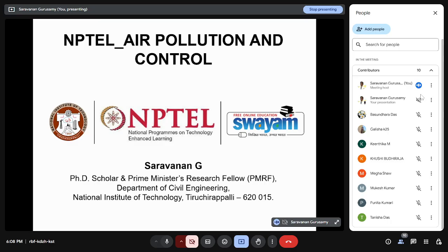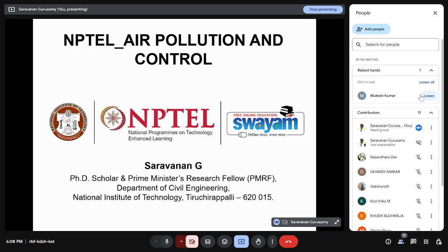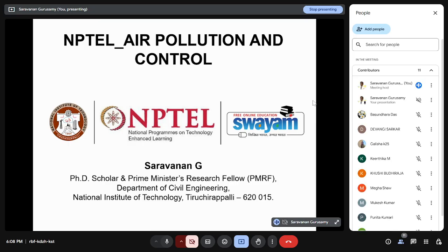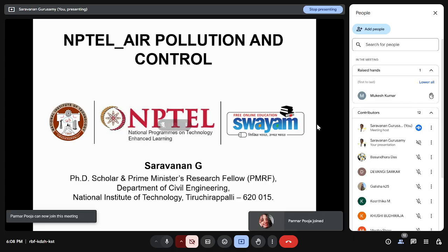Okay. So, in the second week, we discussed the sources of air pollutants, classification, and transformation of air pollutants, like dispersion, diffusion, advection, and convection based on heat transfer. Based on that, we discussed how the air pollution gets dispersed. Based on that, the unstable condition happened, right? Unstable condition is a good dispersion condition for the air pollutants. So our aim is to disperse all the air pollutants. Then only it is easy to reduce the ground level concentration, which has a human health impact.